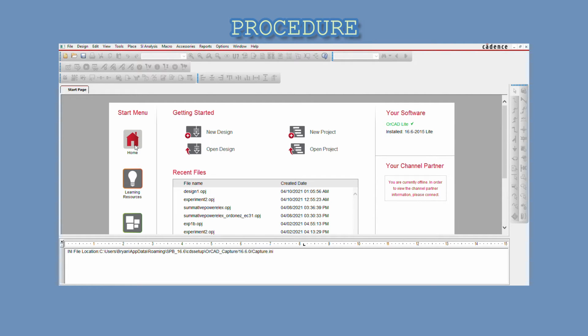The first part of the experiment, we would be using PSpice to measure and see the waveforms flowing through a resistor with a given voltage source. Now let us begin. Open the OrCAD Capture PSpice and click New Project. Choose Analog or Mixed AD, name it as Experiment 2. Then let us select its designated folder. Click OK. Now, we would create a blank project. Click OK.